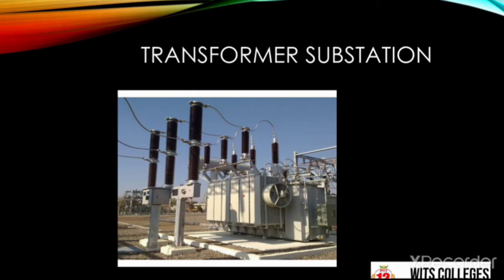Coming to the step down transforming substations, the substation will transform the primary voltage of the electric power system to a lower secondary voltage. Step down substations may be of the regional or local type depending on their purpose and the value of the primary and secondary voltages. Regional substations take electric power directly from the high voltage power lines, and they transmit it to the main substations.